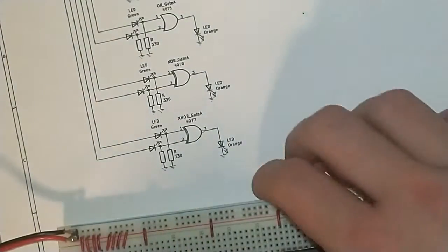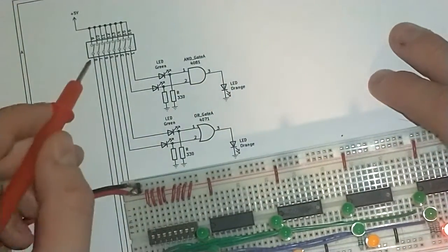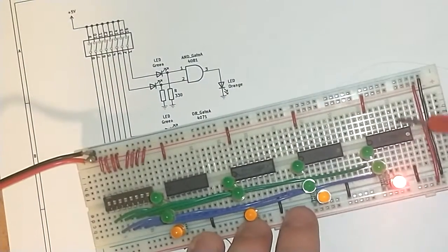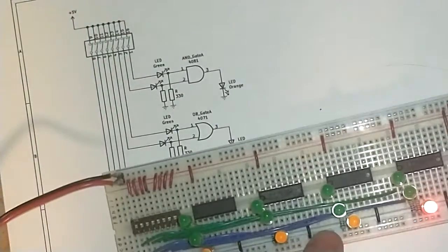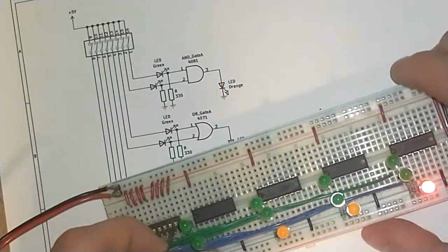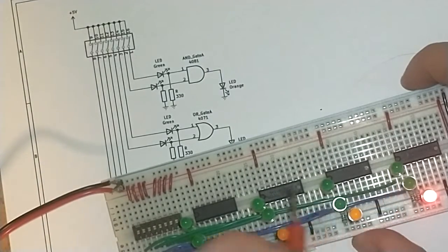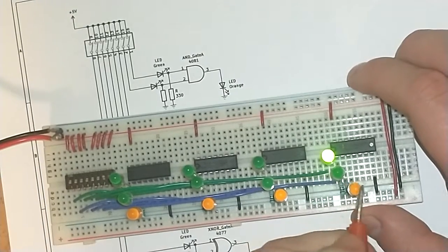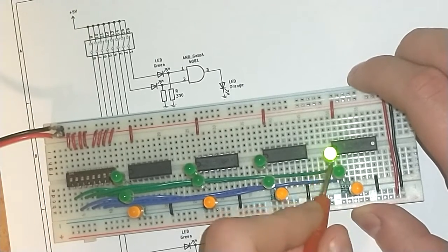So when we take a look at our circuit, these two last pins, 7 and 8, connect to these gate inputs, 1 and 2, through the resistors, as usual. You know the drill. So when I turn on 7, as you can see, this is on because the inputs are equal. They are both 0, so this is 1. When I turn this on, as you can see, this one is now 0, and this one is 1. This one is turned off, because these two are not equal.